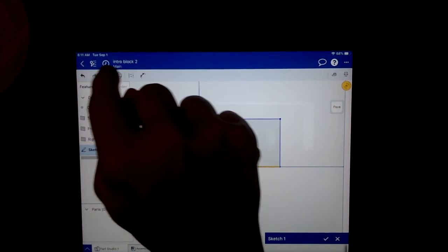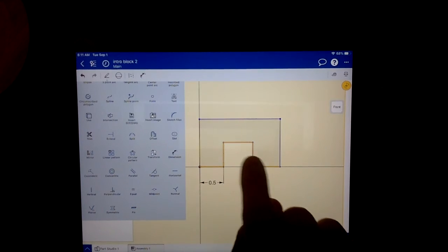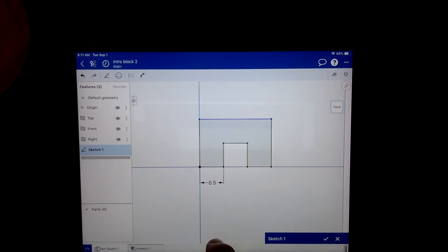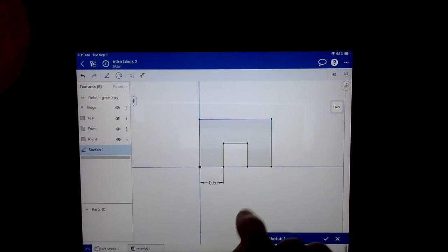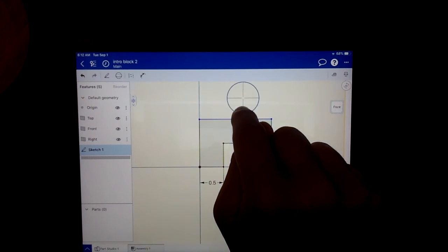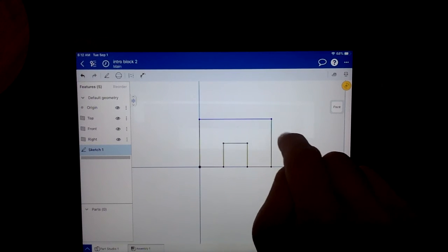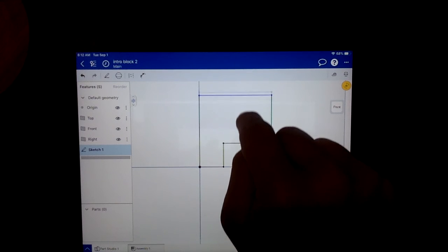So what I'm going to do then is in my sketch menu, there's a constraint called equal. So once I have all of those lines selected, I can click equal, and it just automatically made all 5 lines 1/2 inch. So now if you look, the only dimension that I still need to add is a height dimension right here. I can still drag this blue line and make it taller, right?